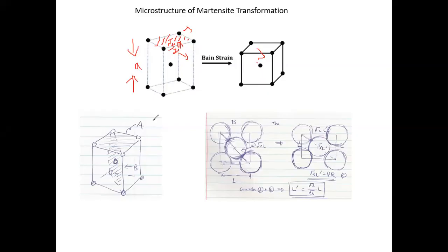So now how can we take into account the packings? I don't know why I labeled this as A and B, but anyway, we have to go one step backward. We start from the FCC structure, and on this structure we need to know how the atoms are packed together. So now we're looking at close packings, but we have to identify what the close-packed planes are. So if I increase the size of the atom, which I think I do here.